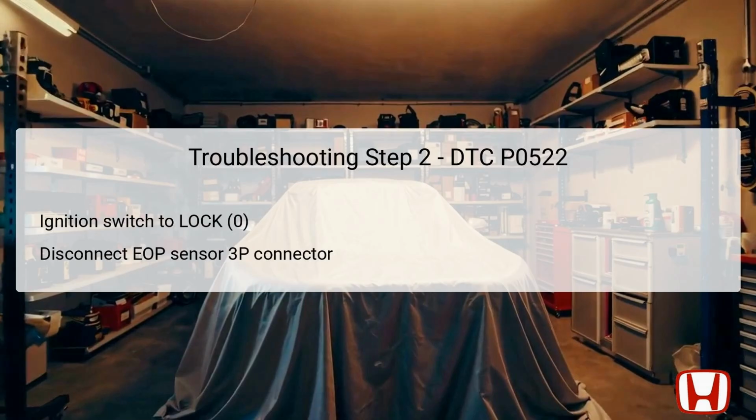Following the findings from Step 1, the next action is to turn the ignition switch to the lock position, designated as 0. This step is essential for ensuring safety while you perform further diagnostic operations.